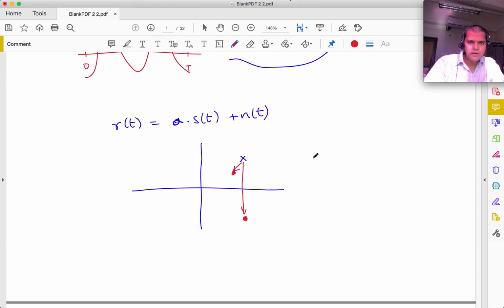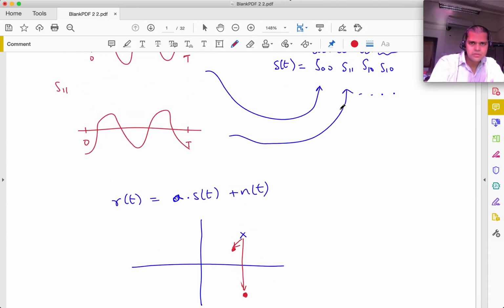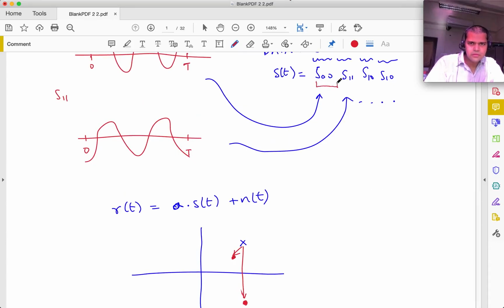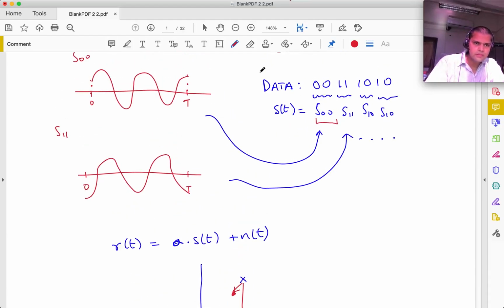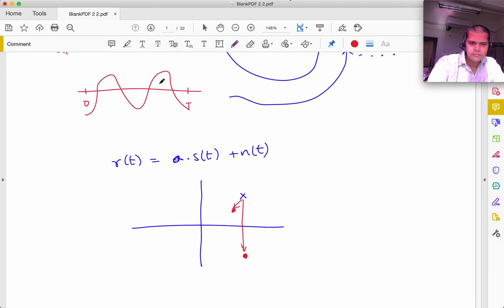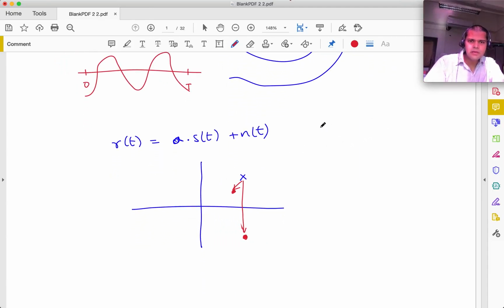Okay. So how do we do that? Well, if we look at each of these components, suppose we are focusing on only one of these symbols, right? So we are not looking at the full signal that was transmitted, but we just look at the signal from time 0 to t, where only 2 bits were sent. So then we get one of these symbols plus noise, and of course this might be attenuated. So we said that what we look at is the x and y components of what we received.